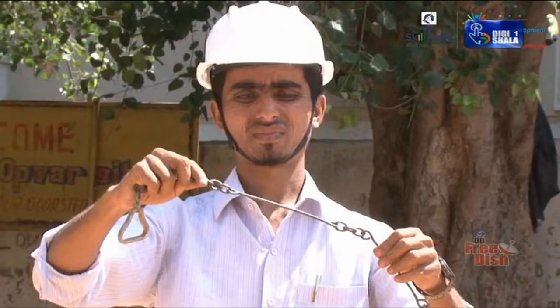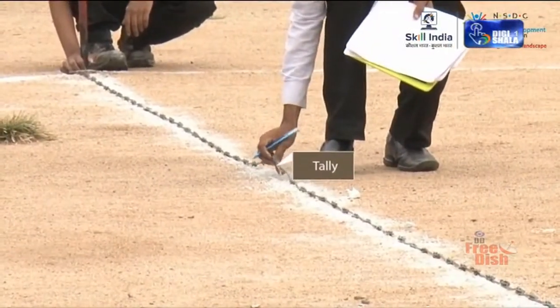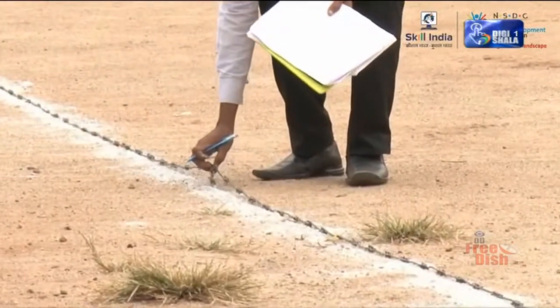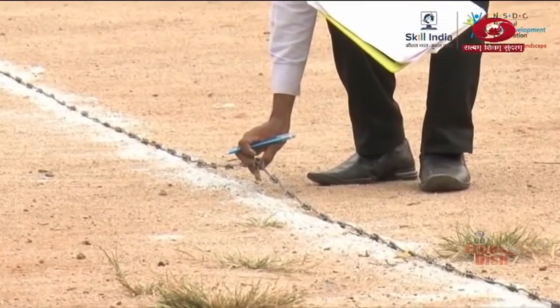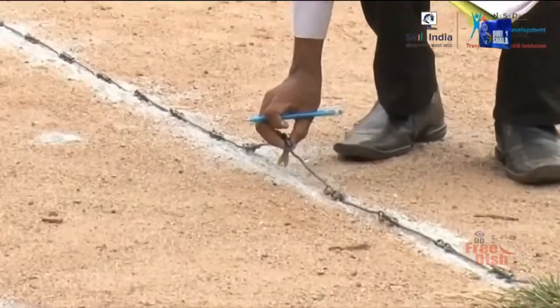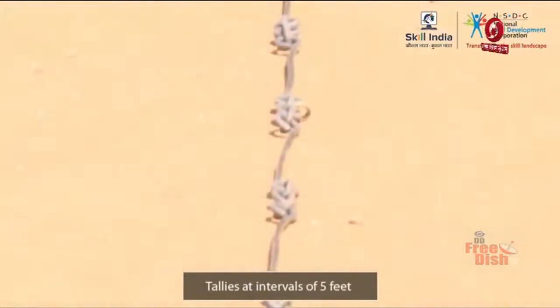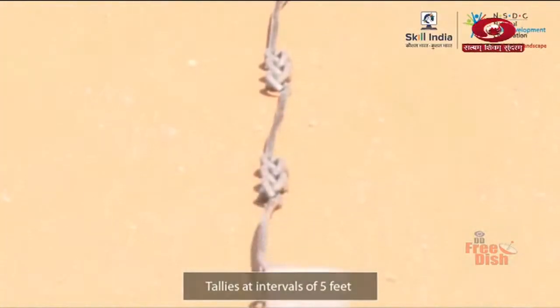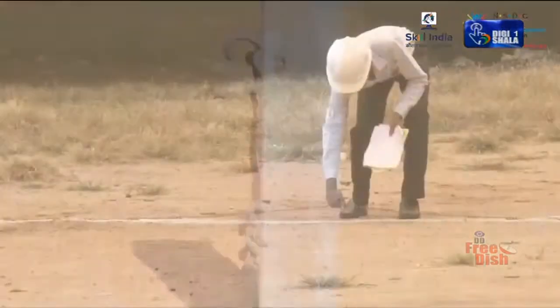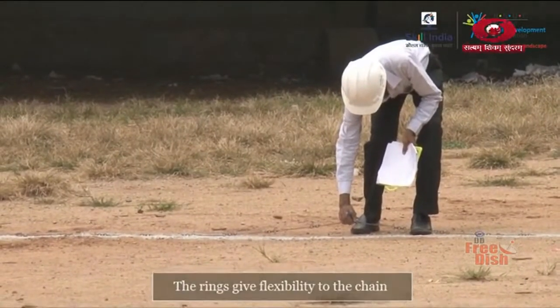These rings give flexibility to the chain. The chain contains markers called tallies. Tallies are pieces of brass shaped like a ring and hung at intervals of 5 feet on the chain. By counting the tallies, the distance can be measured.